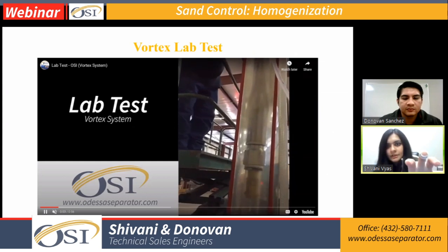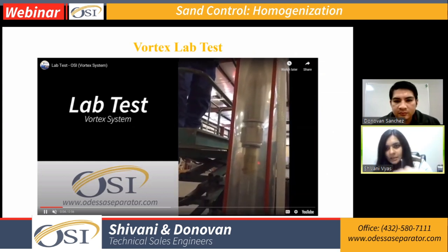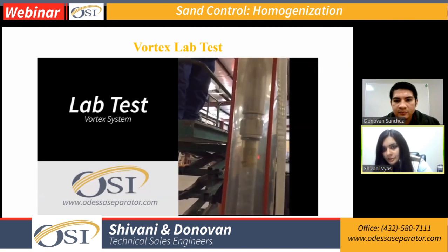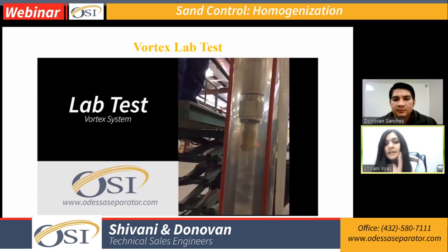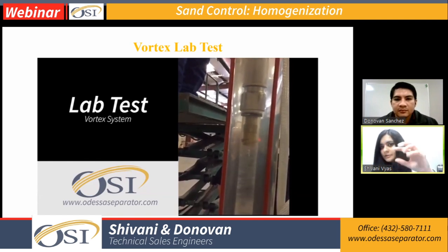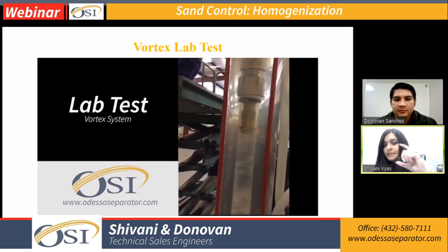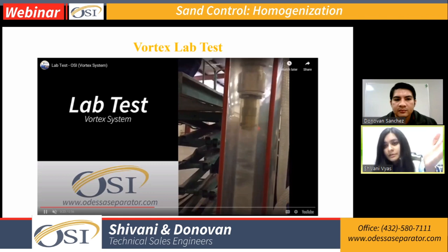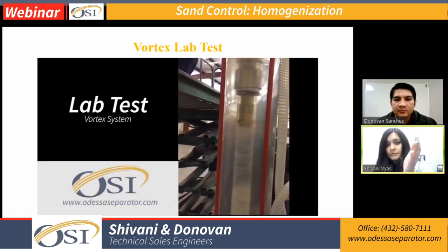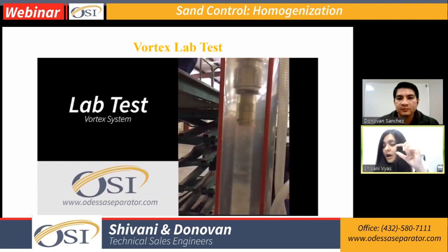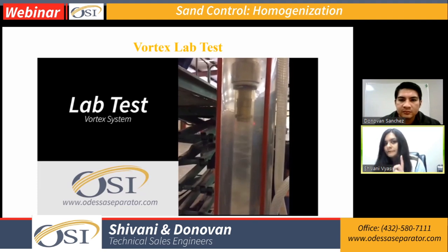You can see that we're dumping all kinds of non-uniform sand. The helix itself is stationary; it's the fluid around it that is moving and creating that centrifugal force. So it is really critical what size we choose for the helix. If it's an ESP producing a few thousand barrels for the first couple of months, it's important that we have optimal spacing between the helix so it can handle that much fluid.